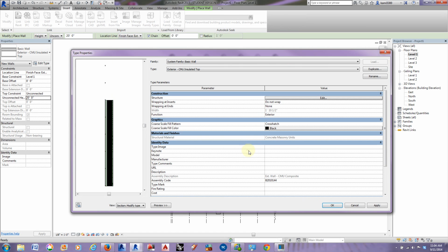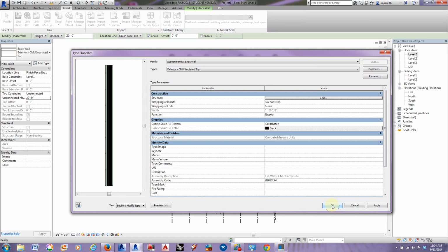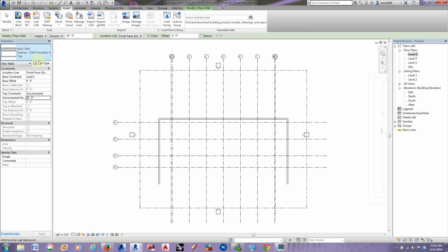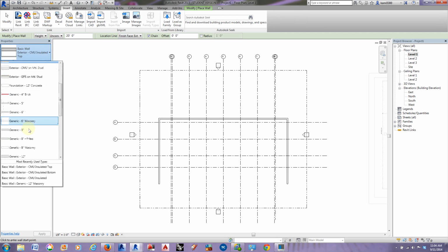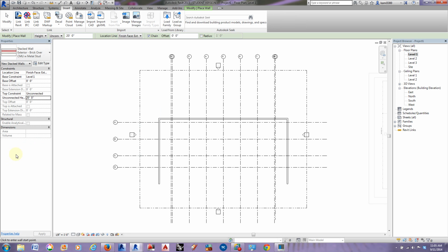and I'm going to click OK. My reveals are sitting up here. So if we change this height to 30 feet, we wouldn't get that error message anymore, because now our reveals are cutting through something. So I'm going to hit OK again, and now I want to go down to my stacked wall and pick this guy,